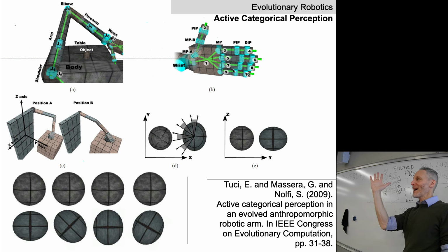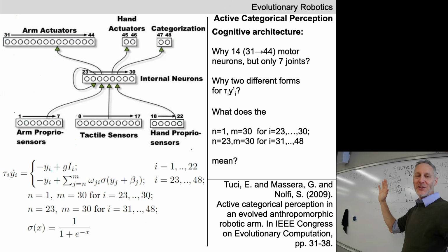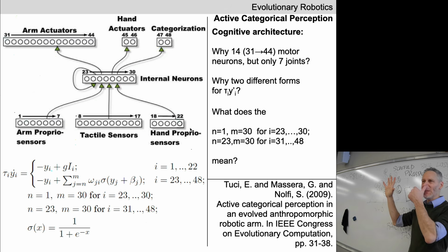You don't grab things with the back of your hand. You can't grab things with the back of your hand. A lot of tactile information clustered on the underside of your hand. That's what they're capturing here in the CTRNN. And then we have an additional 5 neurons that are reporting proprioceptive information. The 5 represent the overall angle of each of the 5 fingers.